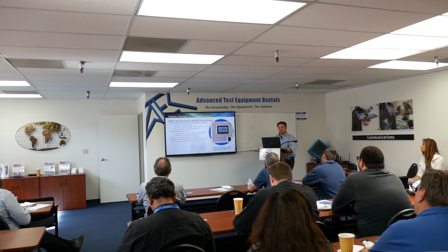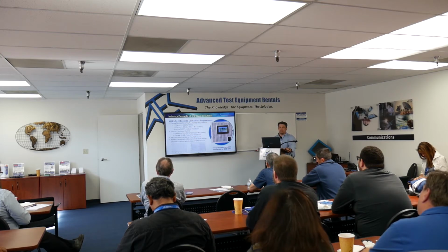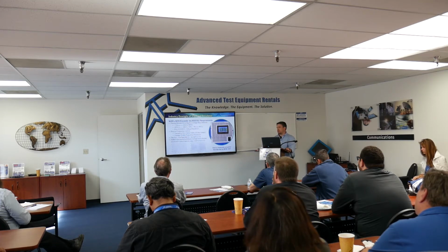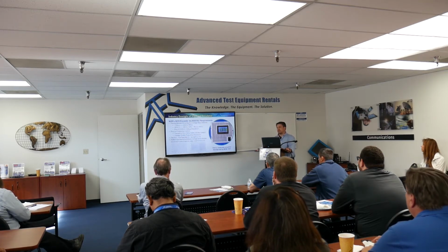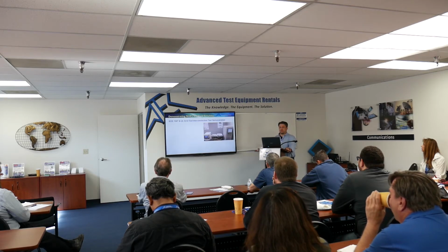Right there. And these are just some examples of some of the abnormal wave shapes you can do with the 9400. And one of the things too is the ability, on the 9400s, you can make voltage changes on your wave shape in about 60 microseconds. It's about how fast you can make a change. You can do those sub-cycle, sub-degree even changes to frequency.